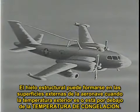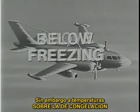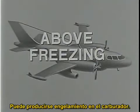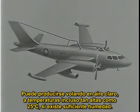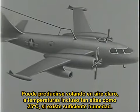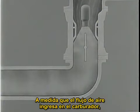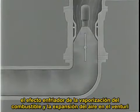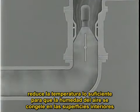Structural ice may form on external surfaces of the aircraft when the outside temperature is at or below freezing. However, even at temperatures above freezing, carburetor icing may occur. This may occur even when flying through clear air with temperatures as high as 25 degrees centigrade if there is sufficient moisture. As the air flows swiftly into the carburetor, the cooling effects of fuel vaporization and air expansion in the venturi reduce the temperature sufficiently to cause the moisture in the air to freeze on the interior surfaces.